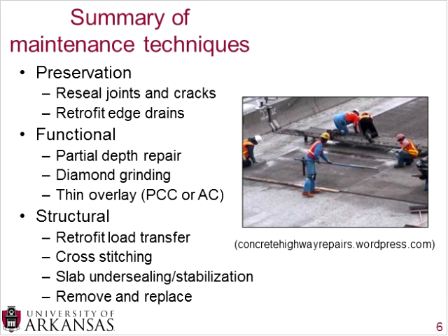Another structural technique is slab undersealing or stabilization. This is where you fill the voids that may occur underneath the slab. So underneath a PCC slab, you generally have some sort of base course or sub-base course. And if that base course or sub-base course moves away, whether it flows away or some sort of void is created, you can use slab undersealing or stabilization to fill that void. Now, you do not lift the slab using this technique. You simply fill voids that are created underneath the slab.